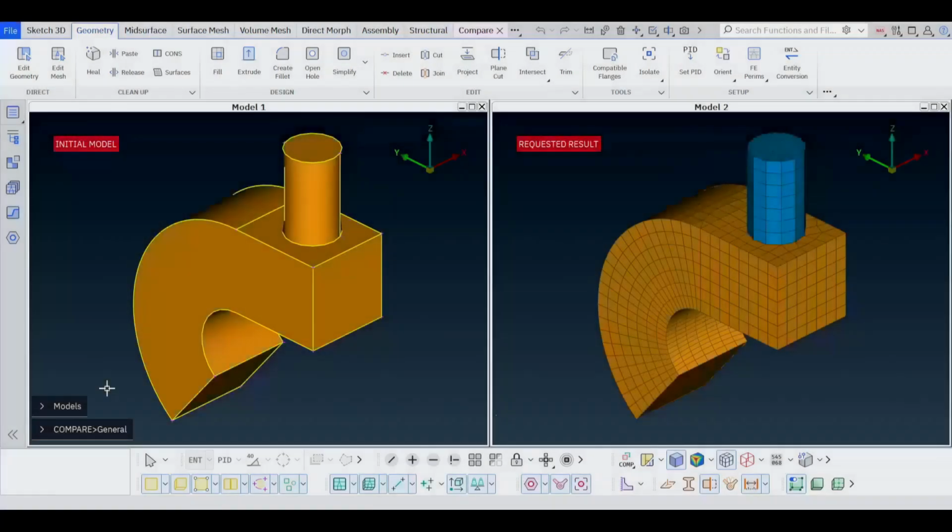The part of the model presented here is composed of two different shaped areas: a cylindrical and an orthogonal section. Due to the fact that the volume here is only one, applying the Map Block function will require further decomposition of the part into two separate smaller closed volumes in order for the mesh to be created.